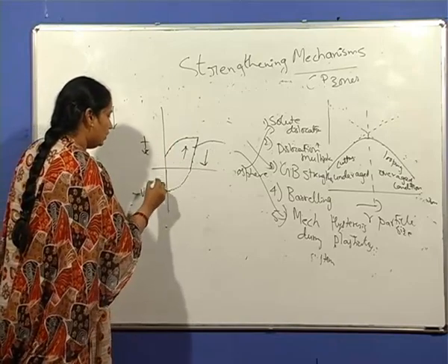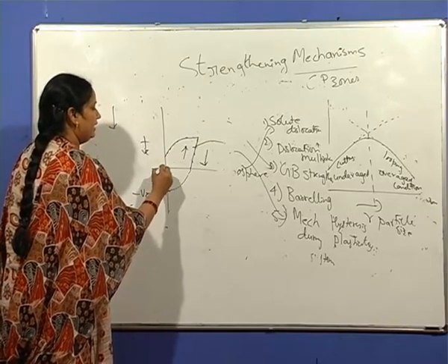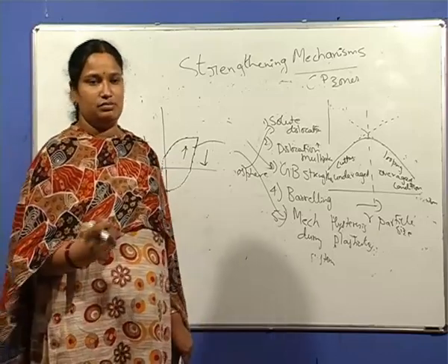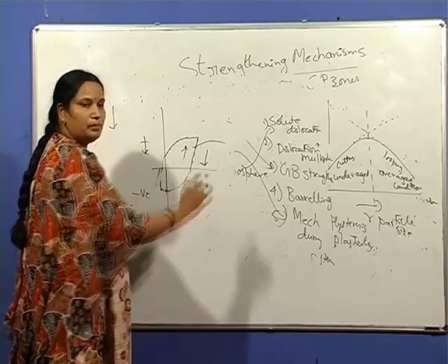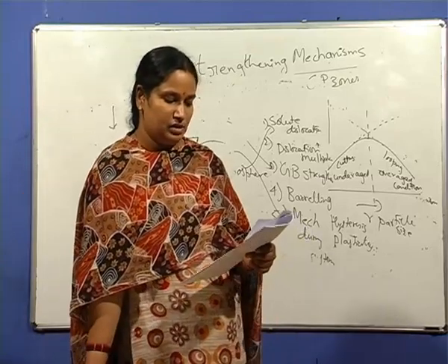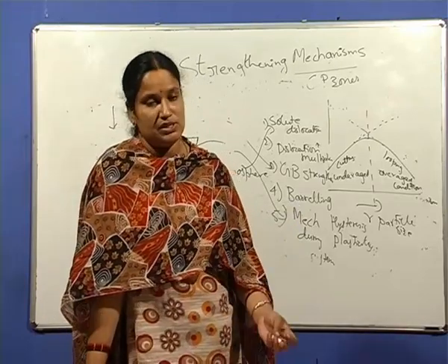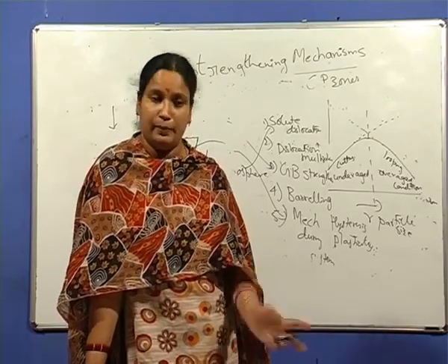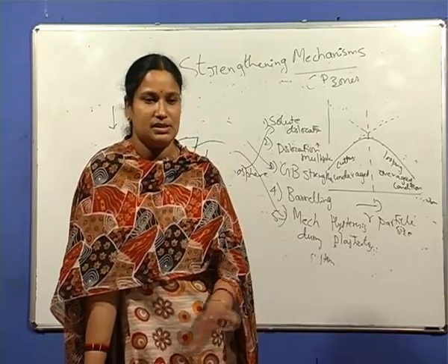And again unload that material and reload it. It forms a hysteresis loop. Neglecting small hysteresis effects, it forms a complete loop. So the Bauschinger effect is related to mechanical hysteresis which occurs during plasticity. So these are the 2 questions which I have found from the year 2007 related to the topics I have discussed till now. There are still topics such as fracture and tensile testing. Since I have not covered these topics, I am not discussing those questions.